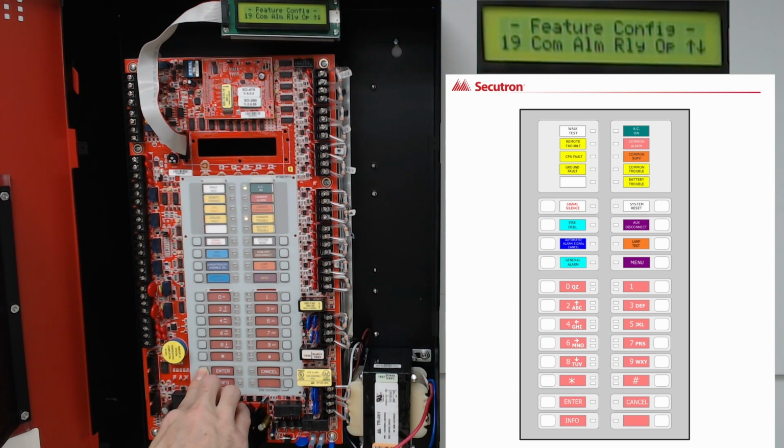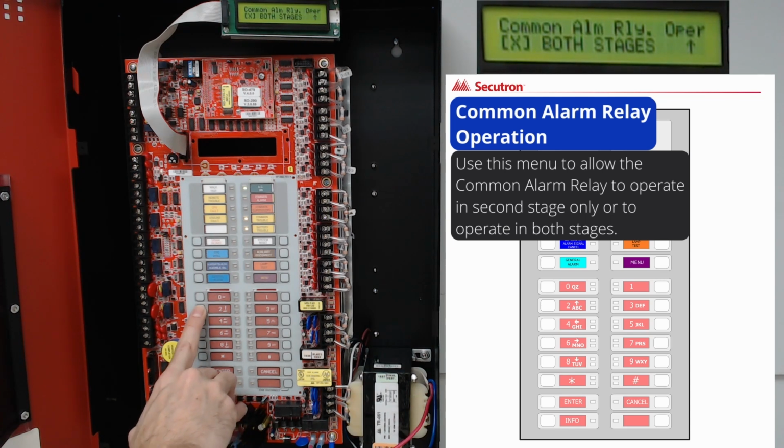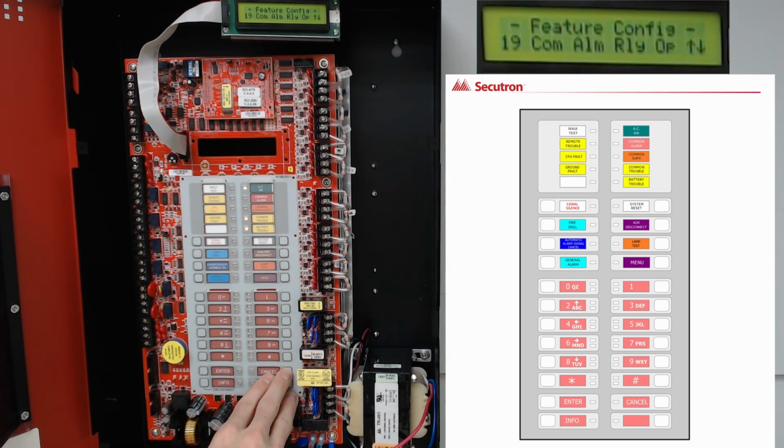Our next option in feature config is common alarm relay operation. By selecting enter, we get to see the options it has been assigned. By default, it's currently set for both stages. That is when our common alarm relay will operate. By pressing the up arrow, we can select for when it will only operate when it enters two-stage. For this option, please be aware of what type of system, two or single stage operation, you've already implemented. By hitting cancel, go back out to the feature config options.